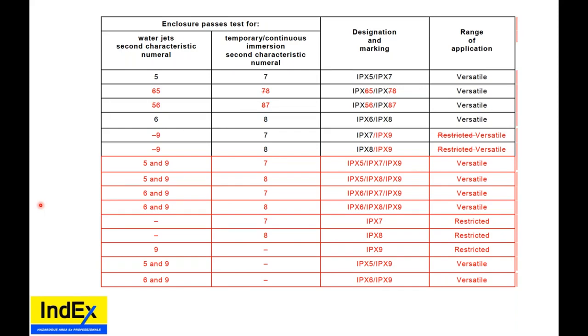That is for the manufacturer and EPC to decide, and the end user. But if I were to have a facility, depending on the area, I would call minimum IP66. But in industry, usually we have instruments at IP65, electrical at 66, motors at 55, but rarely do we accept IP54 outside. Now, glanding, that'll be next week's subject.